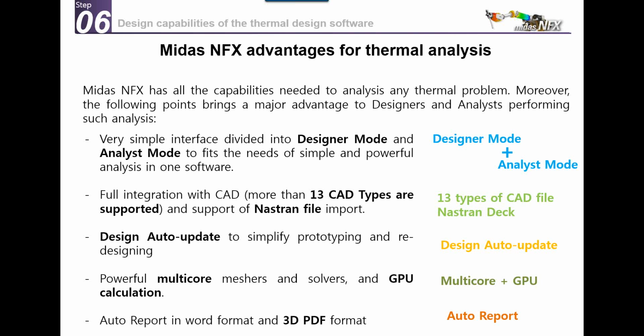NFX fully supports Midas models, for example, so you can import your model from a Midas file and get the analysis to run. It also supports certain CAD model types. So if you have your own CAD software like SolidWorks, Autodesk Inventor, or any type of software, you can import your model inside Midas NFX.